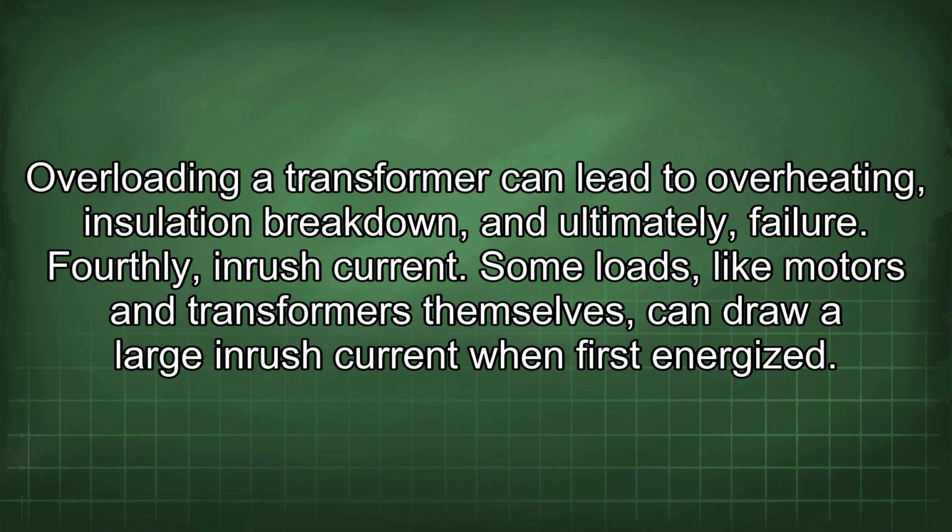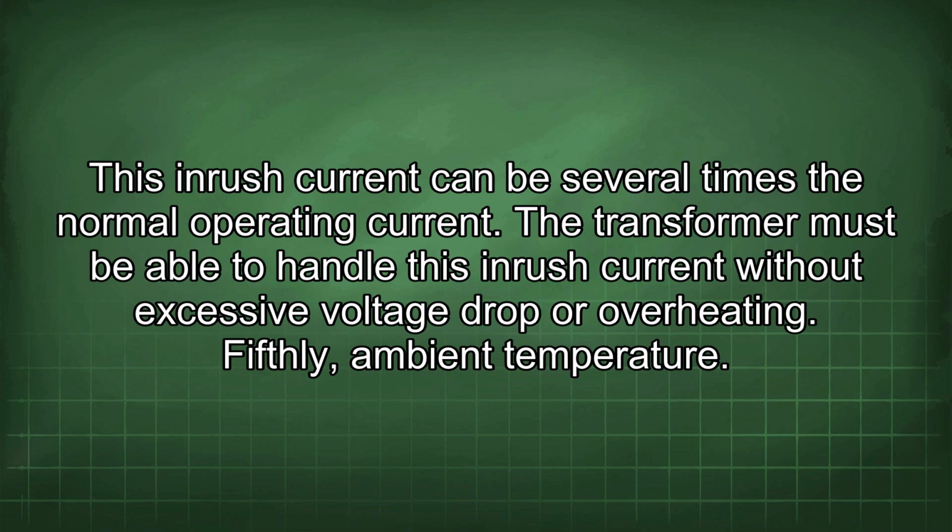Fourthly, inrush current. Some loads, like motors and transformers themselves, can draw a large inrush current when first energized. This inrush current can be several times the normal operating current. The transformer must be able to handle this inrush current without excessive voltage drop or overheating.